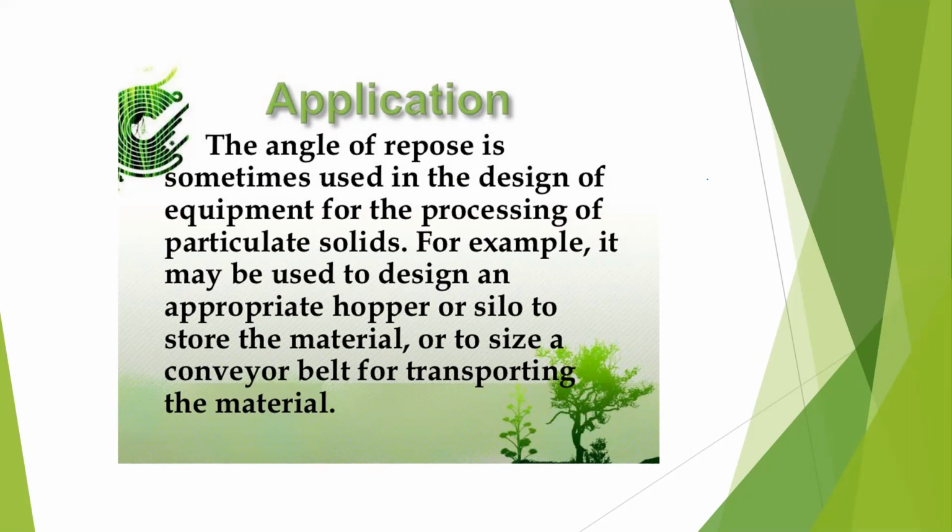It is used to design some equipments. So with the help of that angle of repose only, we can design some equipments. It may be used to design an appropriate hopper or a silo to store the material, or to size a conveyor belt for transporting the material. So these are what? Application of angle of repose. So angle of friction is over, angle of repose is over, which are related here.